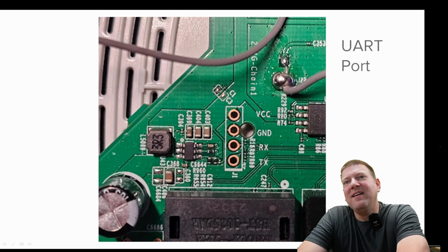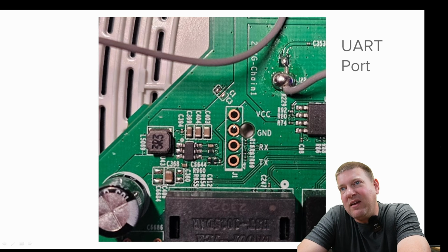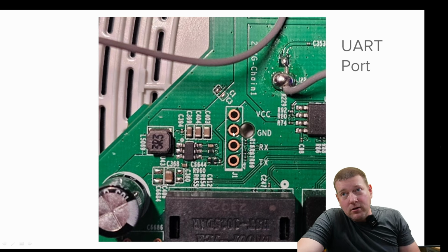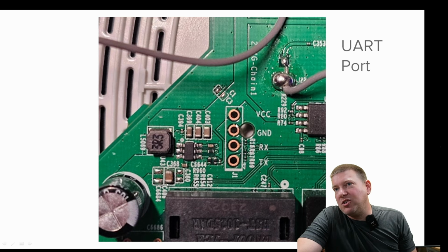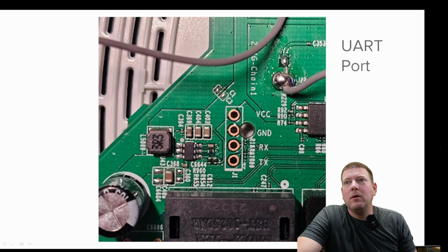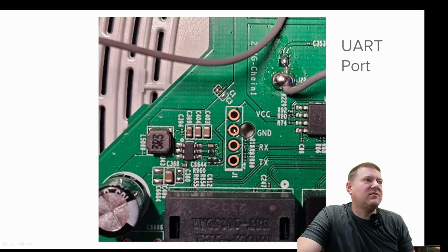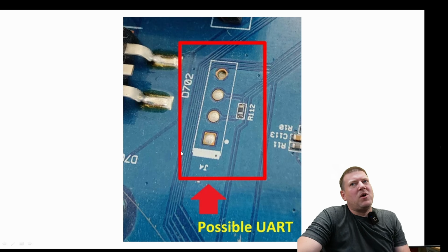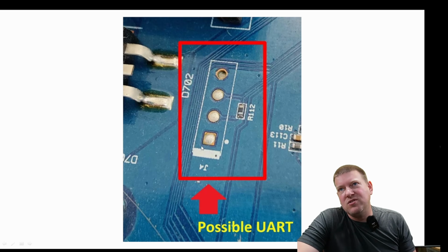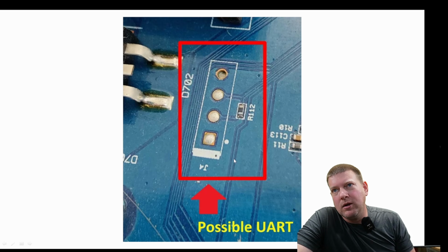That's right. So just pay attention when you see these little junctions between the via. That's called a via, the hole that goes through a board. That little junction right there to the surrounding solder mask, that means that that is ground, okay? But notice on this one, I told you the edge one is normally going to be ground.